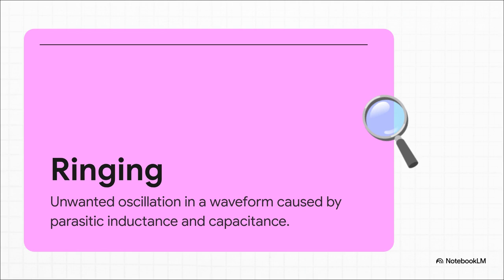So the model is actually built to intentionally create this ringing, that unwanted vibration you see in the electrical signal. This is the digital fingerprint of our noise problem. We create it by adding these tiny, what we call parasitic effects, you know, the unavoidable extra inductance and capacitance that comes from real-world wires and components. Now, our simulation speaks the exact same language as the failing hardware.